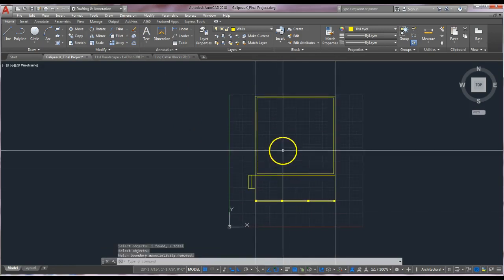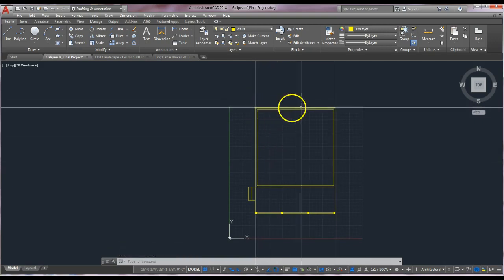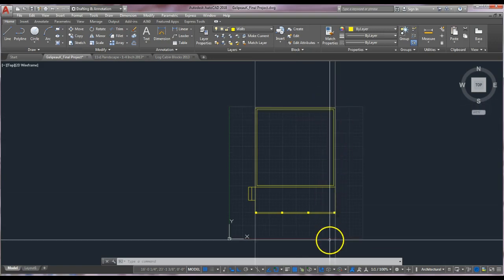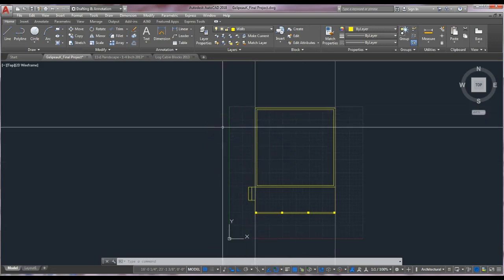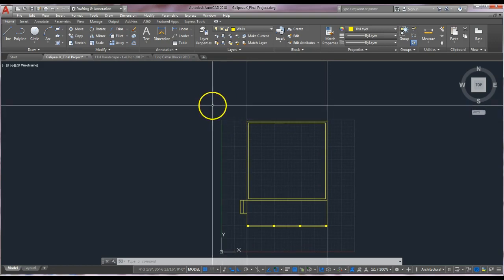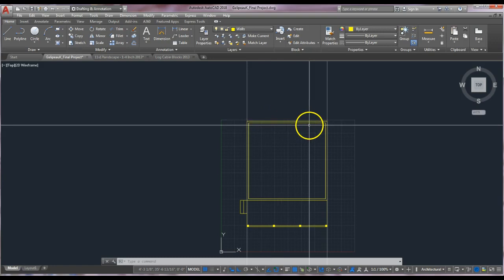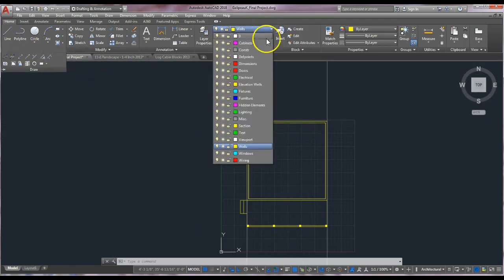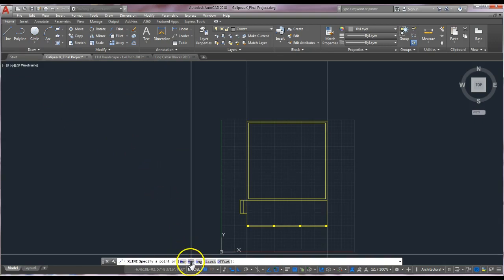All right, now we're going to use all of the dimensions given, and we're going to create construction lines across the top of this plan, and we're going to start with the right-hand side of this plan, and we'll also have some construction lines go along the left-hand side. So the measurements are based on these outer walls and then the midpoints of certain things that are inside the plan. So construction line again, let's change this to our construction line layer. And we want to go to the construction line, and we're going to do a series of vertical construction lines.